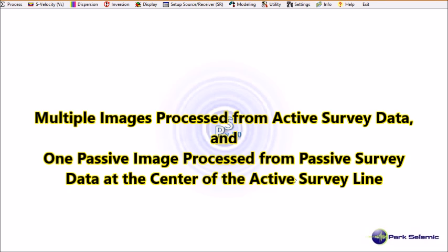And then you process that passive data to produce one passive dispersion image. And now you want to combine that passive dispersion image into all your active dispersion images to provide a constraint at the lower frequency side of the dispersion pattern, which is related to deeper investigation.